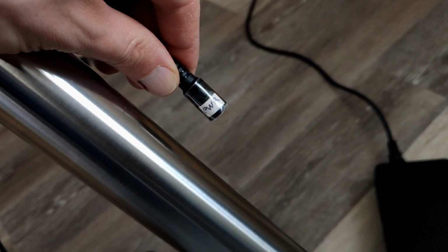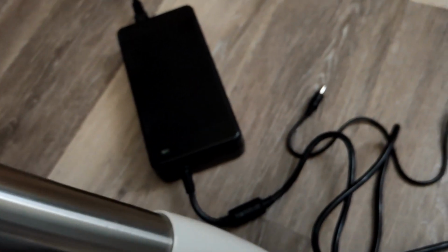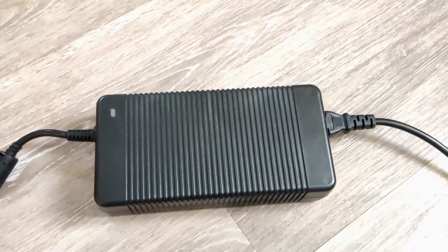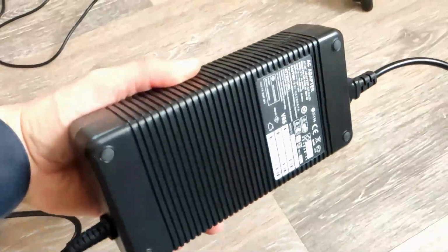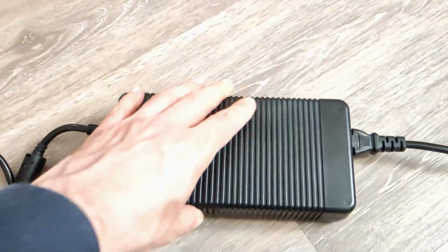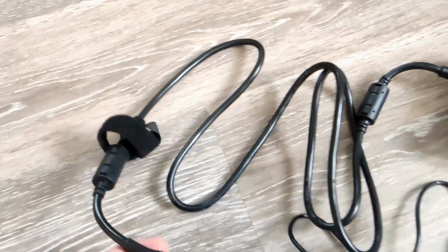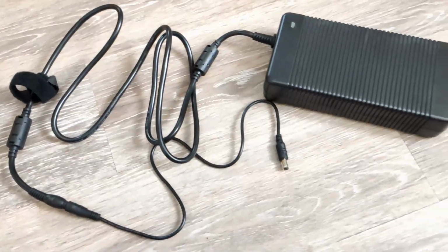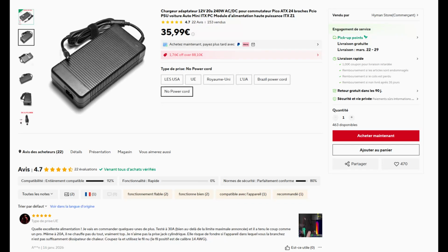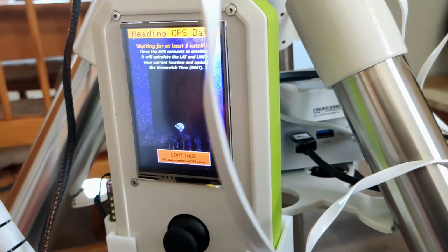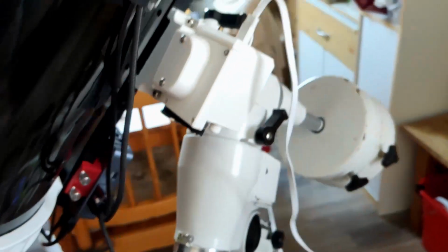Now all that's left is to plug in the power supply. I'm using this one. I'll give you the model number. It's the largest 12-volt power supply available. I had a minor issue with my previous power supply between the Peltier element, which drew a fair amount of current, the Cam87 and the mini PC. I was experiencing voltage drops. This one is rated at 20 amperes and some users claim that it can deliver 30 amperes. According to feedback, it doesn't overheat even at 20 amperes.